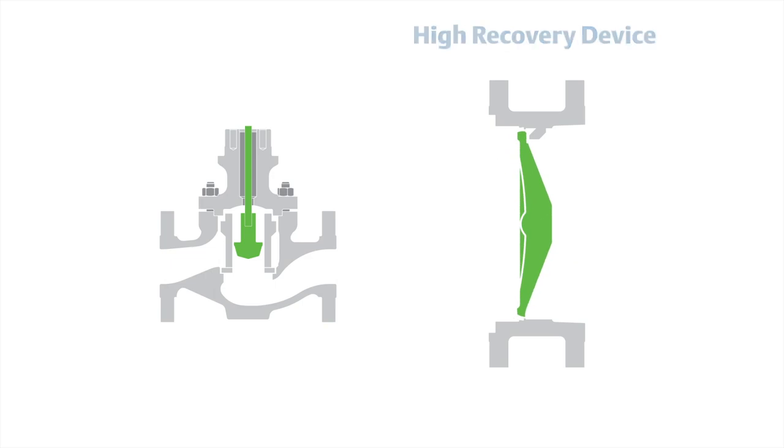If you think about a rotary butterfly valve or a ball valve, as you keep the inlet pressure and flow rate similar, the downstream pressure is going to be pretty much the same as the inlet pressure when it's wide open. That is, the downstream pressure recovers a lot of the initial inlet pressure. So that's called a high recovery device.